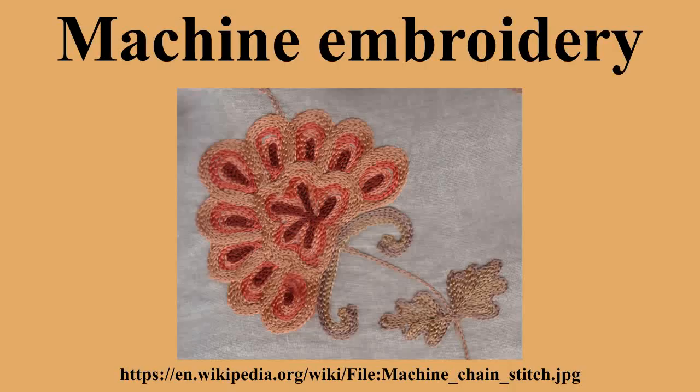Stabilizing the fabric to prevent wrinkles and other problems. The fabric must be stabilized. The method of stabilizing depends on the type of machine, the fabric type, and the design density. For example, knits in large designs typically require firm stabilization.